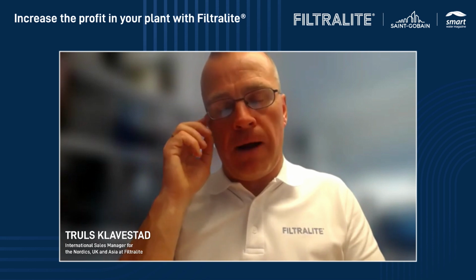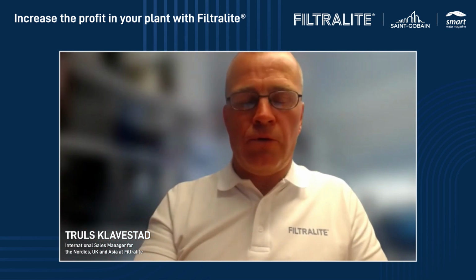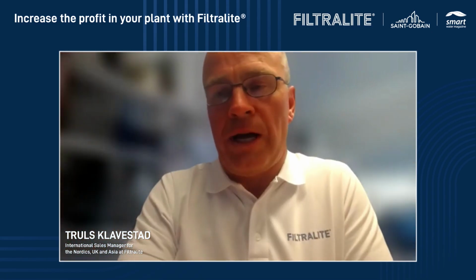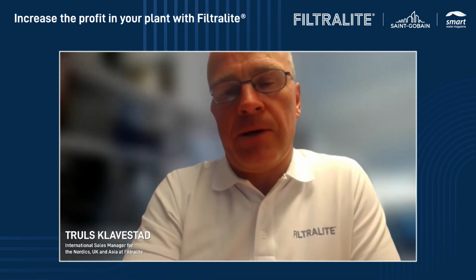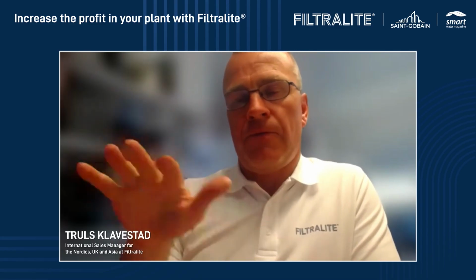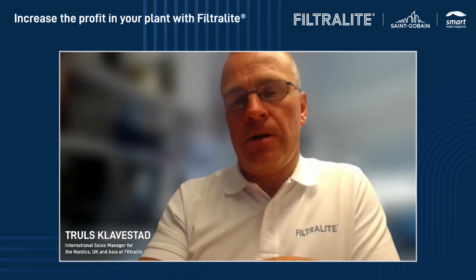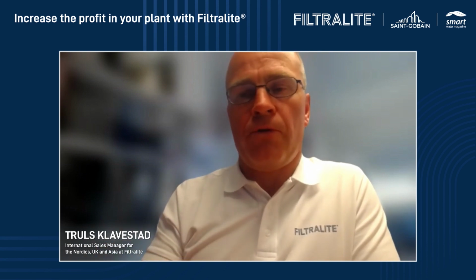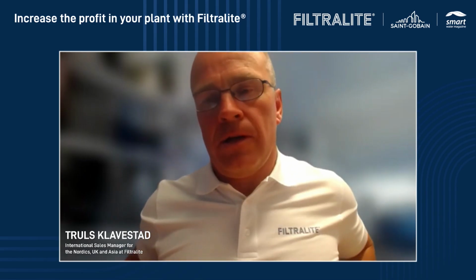Do a proper backwash, but keep in mind if you have sand, replace it with Filtralite. You need to reduce the frequency of the backwash. If not, you will lose the material, and you don't want to do that. So that is the only thing to keep in mind, is that you reduce the frequency of the backwash pump. So when you've done a proper backwash, start slowly and rather increase the frequency between each backwash until you see that you get less and less dust. And then because it's very easy to see if you have dust on the top or not when you drain the filter. So there are two options: backwash the dust or do a skimming.